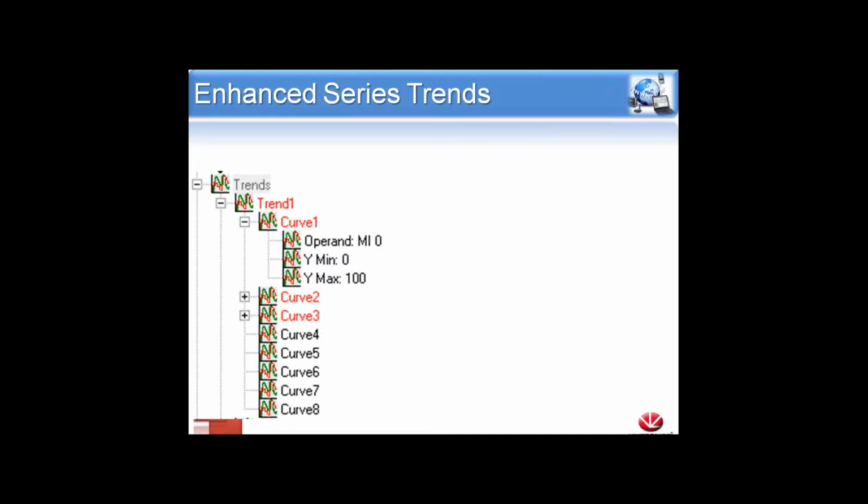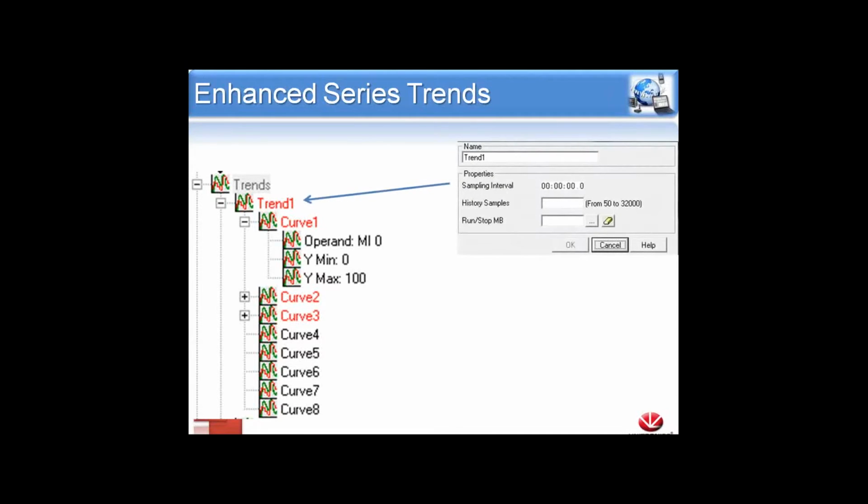To set up the trends, it's very simple. It is all done within VisiLogic. On the left-hand side of VisiLogic, you'll see what we call the Project Explorer window. You'll see there is an expandable option called Trends. When you expand it out, the first topic you'll see is the individual trends. This is going to be the graph we're actually going to draw on the screen, or our plotting area.